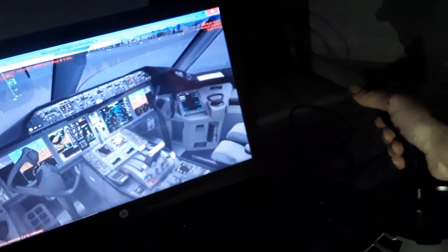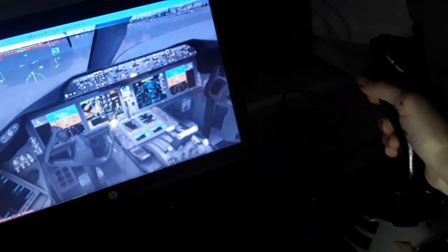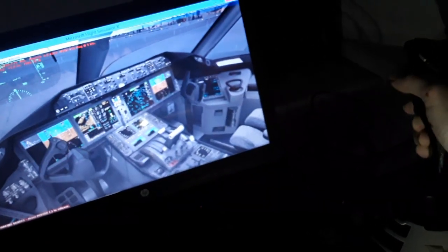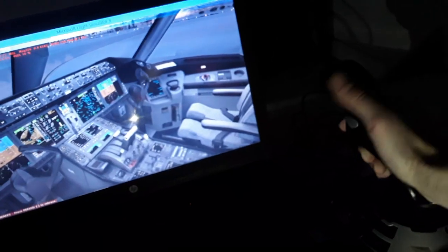So we have, you can see the captain and the first officer move together in flight. They're interconnected. All flight controls, not like in the Airbus where we have the side stick priority, and you can use either side if you need, unless you have a failure. They all move together. All flight controls, elevator, rudder, spoilers, rudder pedals. So maybe I will show you one more view of the flight controls of the Boeing 787. Then I will show you the rest of the systems of the aircraft.